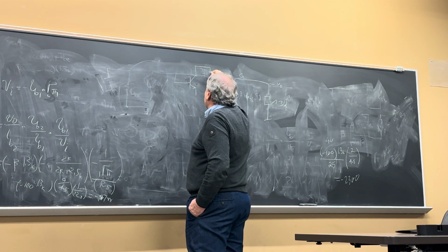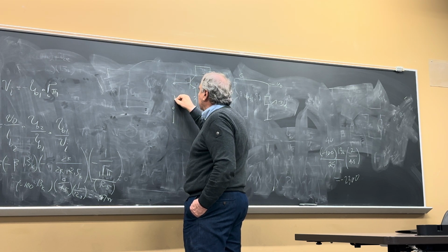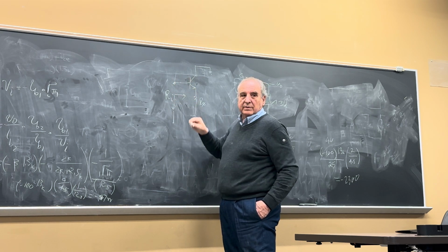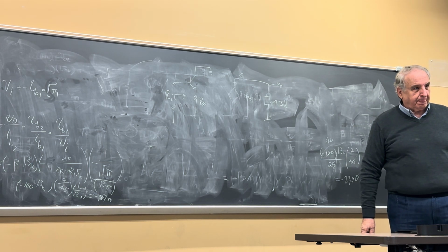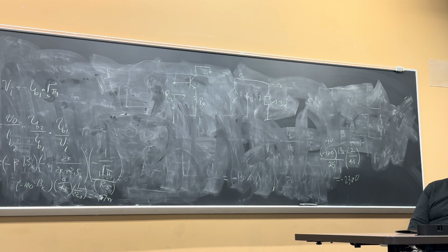This is AC equivalent circuit, and I have RX here. What is the input impedance looking this way between these two nodes? What is R Thevenin? Somebody come up here, do it. How do you find input impedance for anything? You apply test voltage, you measure the test current, it's VT over IT, right?